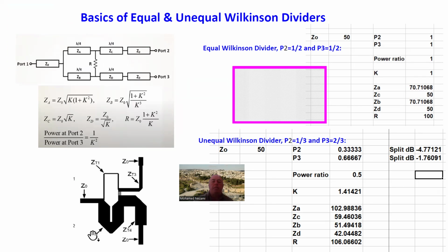And these impedances in here, like I show in the cartoon here, you end up with low impedances sometimes, with a high impedance. And then, of course, this additional lambda quarter line in here, that's just in case your output is not 50 ohm, is not Z0. In a lot of cases, if you're 50 ohms in here, you end up ZC and ZD are basically 50 ohms.